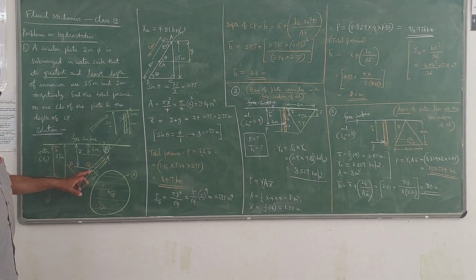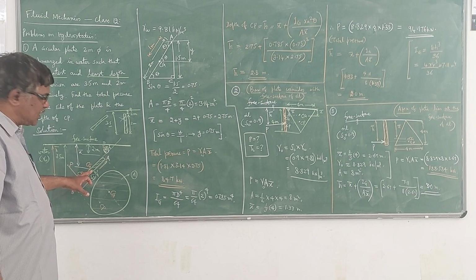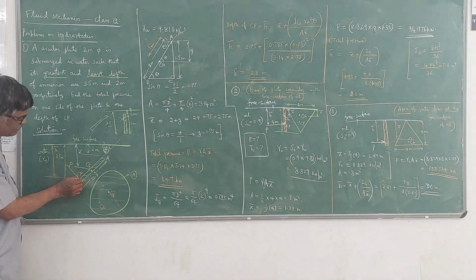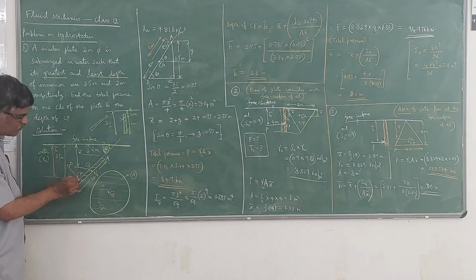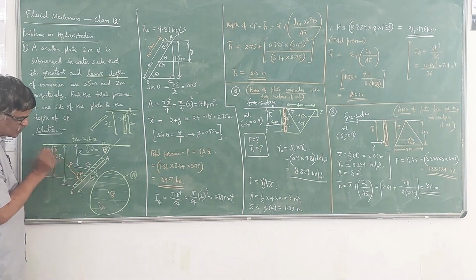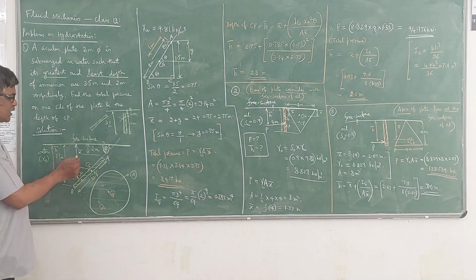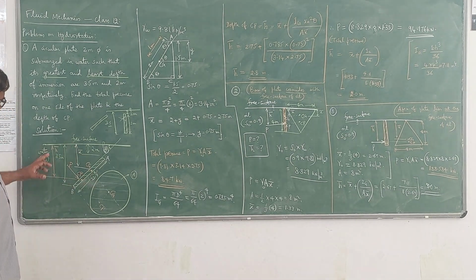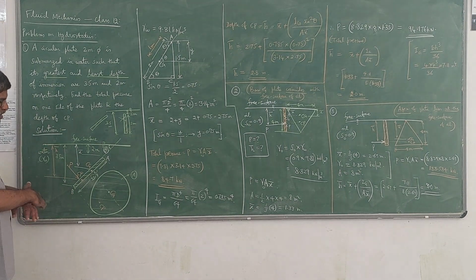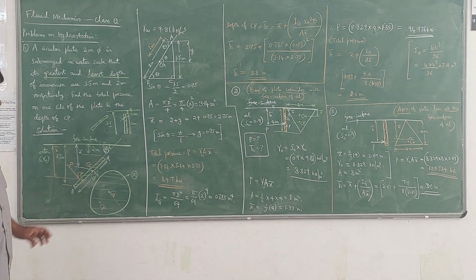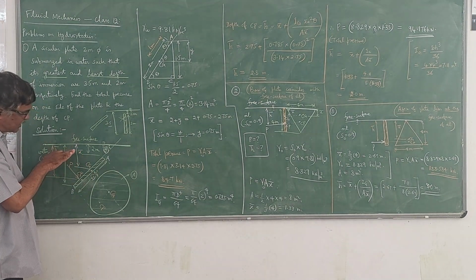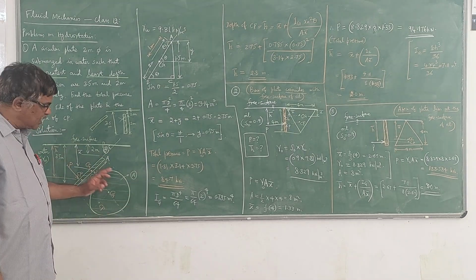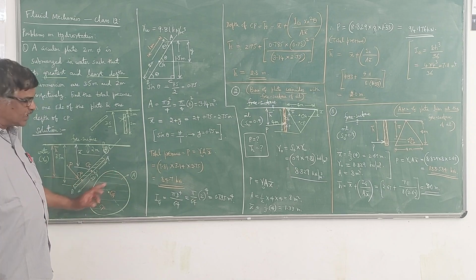Now the center of gravity of the plate, we know that it exactly lies at the geometrical center. And center of pressure always lies below center of gravity, somewhere here. At that point, your total pressure force will be acting normal to that, so at right angles to this. Now this is the diagram. Now x bar is the depth of center of gravity of the plate from the free surface. H bar is the depth of center of pressure from the free surface. P is the total pressure force. And your projected area, this whatever water is there, that is exerting pressure on this entire area of the plate. That area of the plate you can see here is pi d square by 4 since diameter is d.